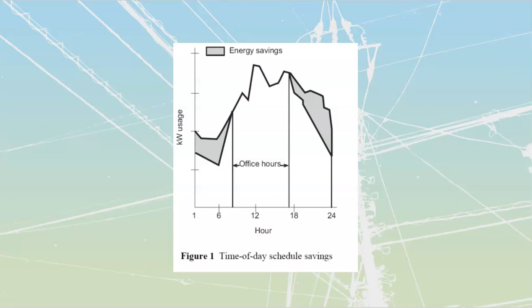The first one over here is going to be our time-based management. And time-based management basically says, hey, when is your building active? When it's not active, shut off the unnecessary lights. This is no different than your dad coming into your room and saying, shut off that light if you're not using it. Why would we have lights and unnecessary equipment on if we're not using it at any time? There are massive amounts of time that offices, buildings, etc. are going to be unoccupied, just weekends and out of office hours themselves as well.